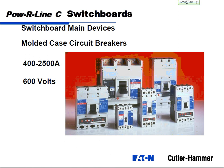But so your molded case breakers, which is this type, molded case being it's all plastic on the outside, can go up to 2500 amps. But the 2500 amps have this big operating handle, and they're very tough to operate. You have to put like an extension on that handle to get that thing to move, just because there's the springs in there. Make it very difficult. All manually operated.